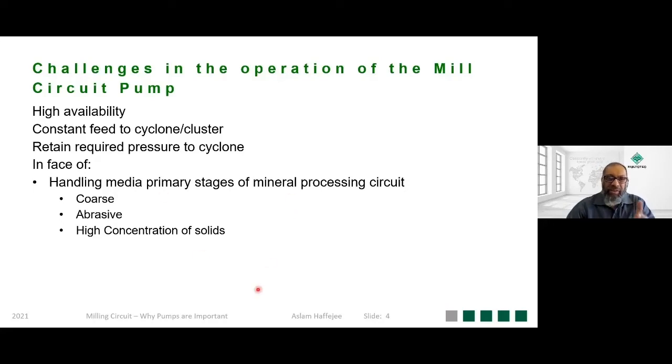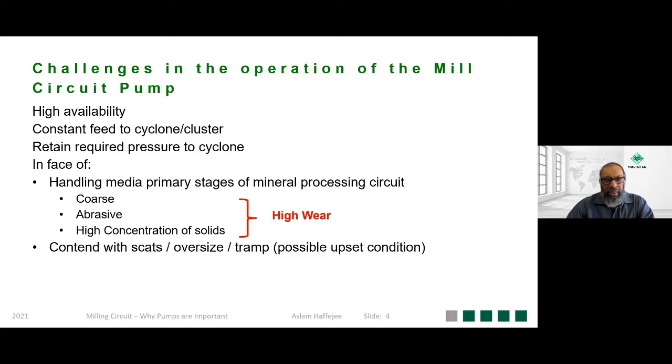Now, all these factors combined give the pump a nice problem of high wear to contend with. And over and above this, you might have an upset condition where the pump has to contend with scats or oversized or tramp material which might come through after the mill.